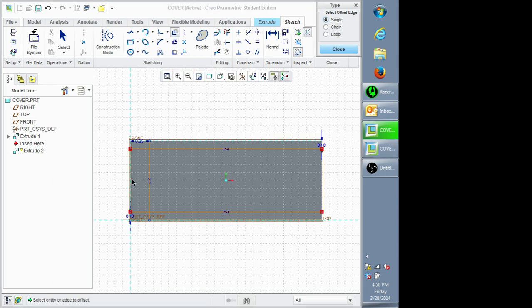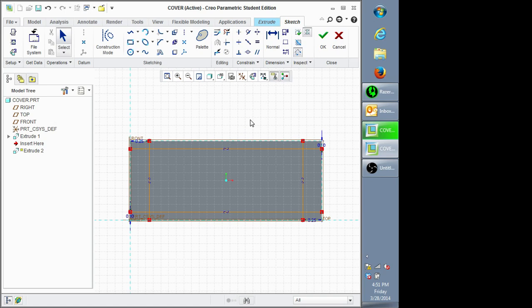Okay, this little window here that pops up, you can just close out of that. That'll close it too. Or you just click the middle button, and it'll close. So to get rid of these extra edges, you want to use the segment tool that I mentioned in the first workshop, and it'll let you delete these little edges back here. You just hover over them until they're highlighted, and just click them, and it'll delete them without having to delete these.